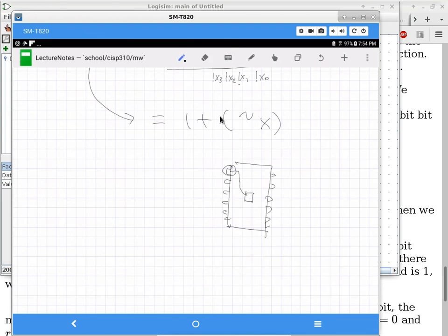So when you have a design like this, you have a wire that is not connected and it's going to the input of something. It is going to fluctuate all over the place. Is it a 0 or is it a 1? It depends on many things. Did you turn on the microwave? Is your cell phone ringing? Is it a blue moon? The phrase, once in a blue moon, now we actually understand what it means.